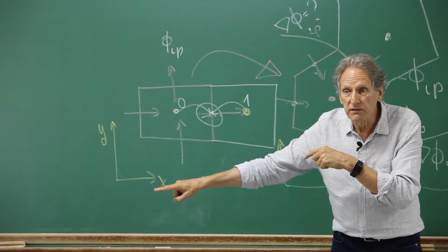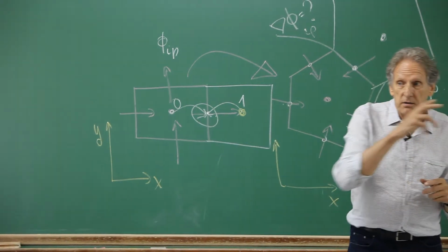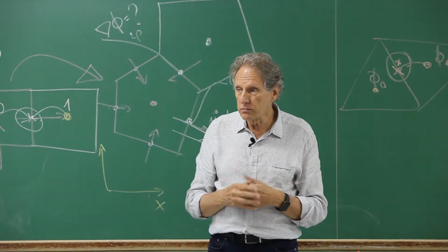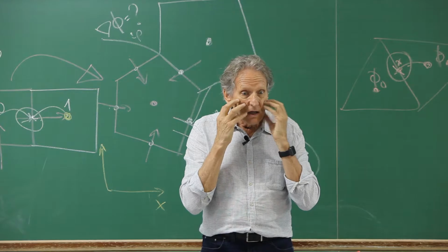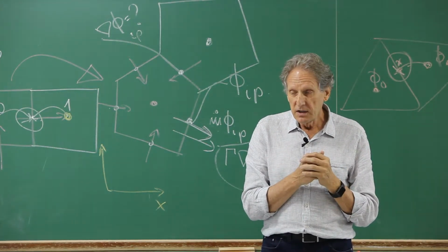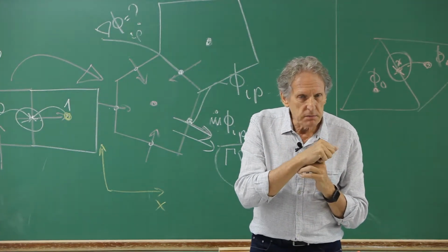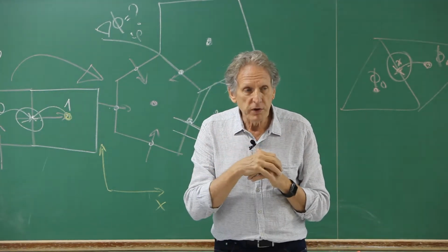Otherwise, it would be the derivative, and you would need a very fine grid. But if you are concerned about the main flow in this room, to see if it affects you, if it makes you uncomfortable sitting in some places, it doesn't matter if the velocity is 2 meters per second or 2.3.